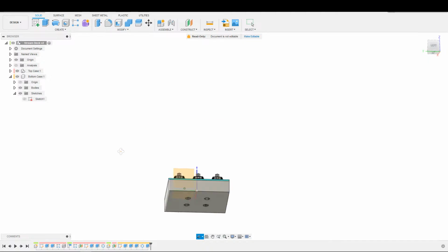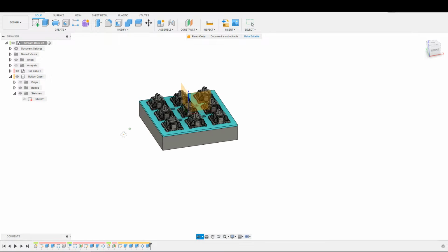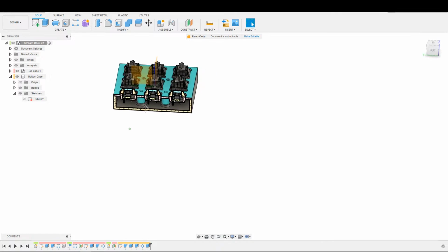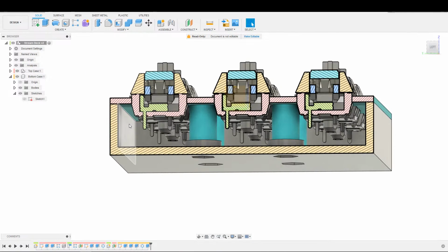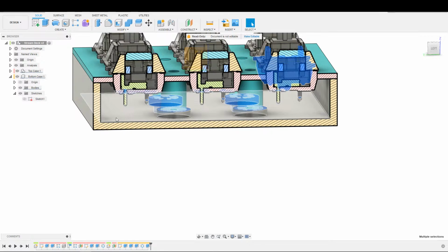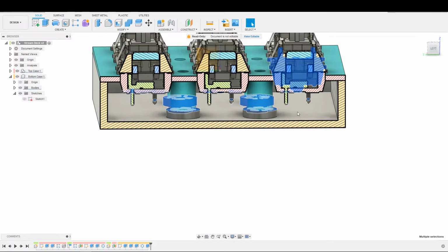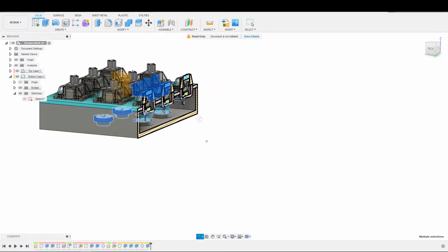So let's just make sure we have the front reference correct. So here's our front reference. We want the slides to go on the side. And let me just actually check, so it's symmetric all the way around, so I should be able to take any section analysis. And actually, yeah. So my thought was to have a slot in the side here, okay? And a ridge in the front side to stop the wheel from rolling out the front side, right? So it can't roll off the front. And then putting a screw just to act as a pin through the back side here. And I was just looking right here just to make sure we have space back here. That pin being there so that the rollers do not roll off of the next lower row.